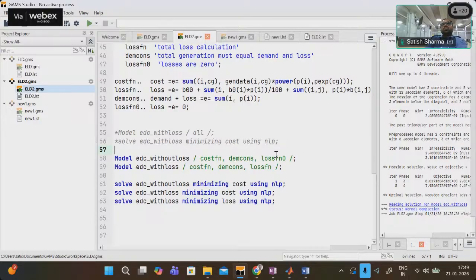About unit commitment, for the entire day we have a rough estimate of what the demand will be and what the reserve requirements will be. Again, the estimations are on the upper scale only. With that particular estimation, the system operator commits certain units. That is what unit commitment basically takes care of.